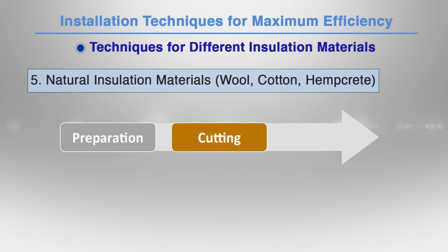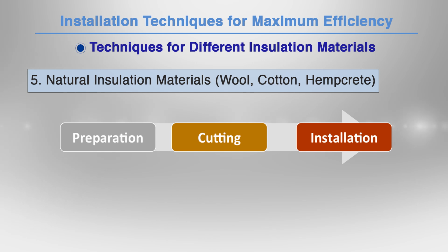Cutting: cut natural insulation material to fit snugly within the cavity, similar to fiberglass batts. Installation techniques: install in layers, ensuring even coverage without compression. Natural materials often require additional fasteners or netting to hold them in place.